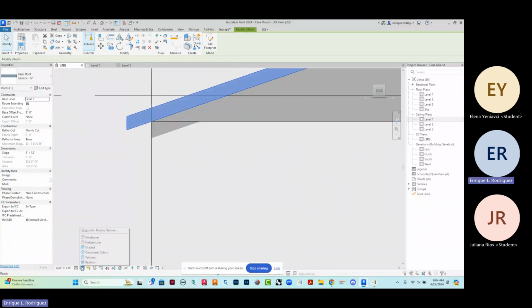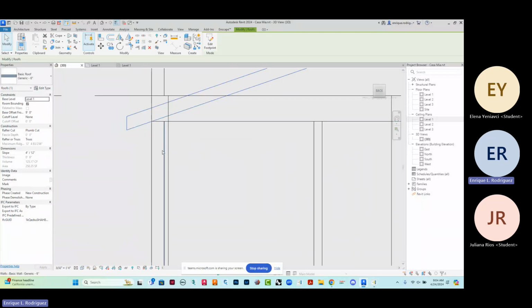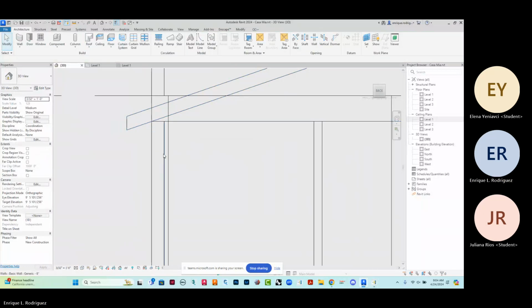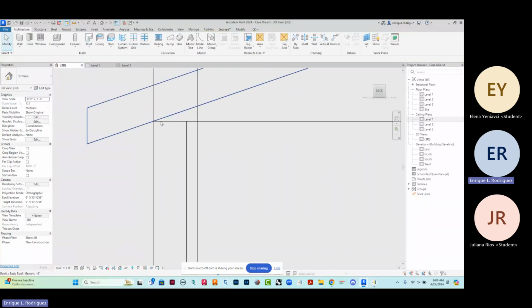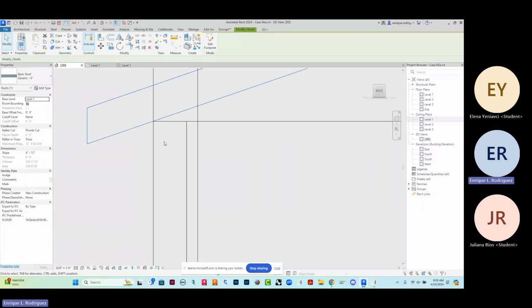And what I'm going to do is go to wireframe so I can see the thickness of my wall right here. Okay, that's the wall below it. And we can't have this bearing condition right in here. We would probably have to bring this down. And since it's a wood to wood connection there, because we'd have a double top wood plate, these are frame exterior walls, I probably need 2 to 3 inches of bearing. If it was a masonry wall or a concrete wall, we would need a different number. And those are usually regulated by standards and codes.